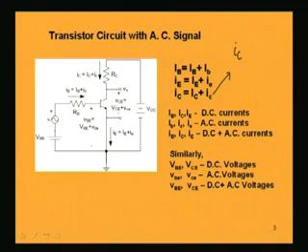One is the DC component, and on it will be superimposed the AC component. Here, if we consider small ic, this is nothing but beta AC times small ib, where beta AC is the AC beta value, and this is, magnitude wise, not very different from the DC beta value.